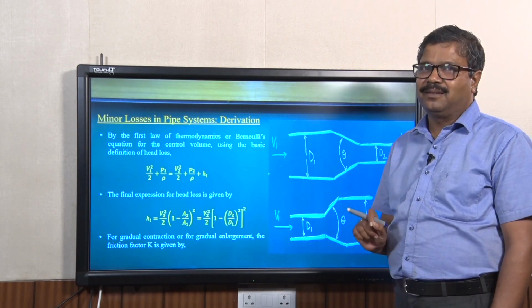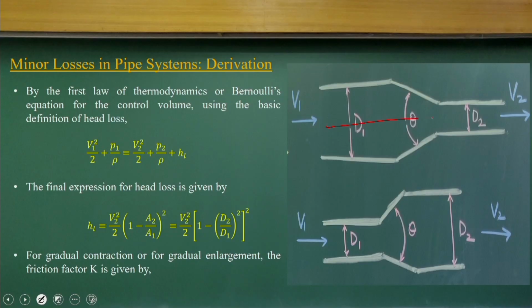Now I will apply Bernoulli's equation along the straight line. Since the streamline is horizontal, you don't have an elevation head component. You have the pressure head component and the velocity head component. That's what you equate at P1, P2, V1, V2, plus the energy loss component, the head loss component. The flow comes from section 1 to section 2, and through the flow there are energy losses. That's what we quantify with HL. Because of that we call it the modified Bernoulli's equation.